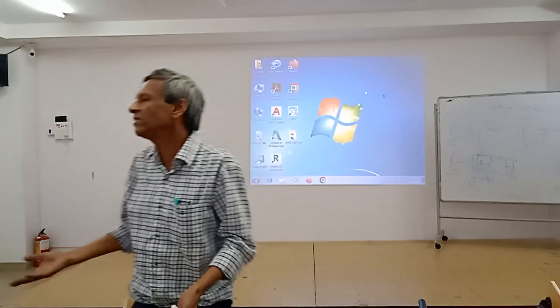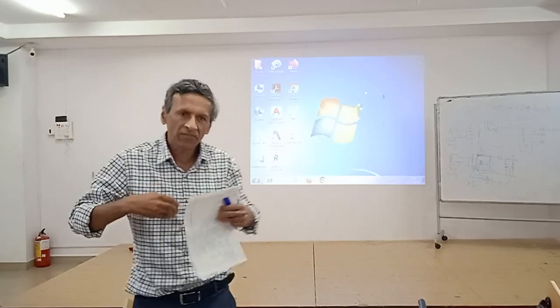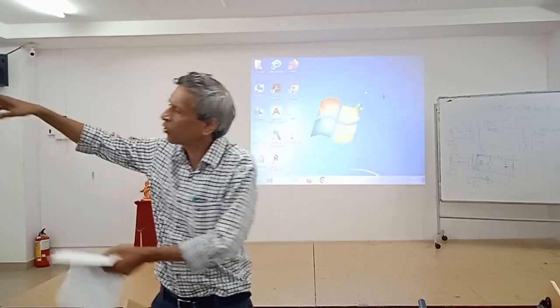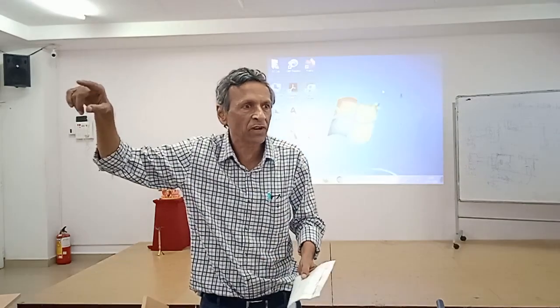Now the BLDC does not have a brush, no commutator. So how to judge the rotor position? Unfortunately there is not enough time, otherwise we could have one hour lecture only on BLDC operation. Anyway, there are 3 Hall sensors. They are kept at 120 degrees in the stator, and whenever the rotor magnetic pole, north or south, passes through, the Hall sensor will change its polarity.